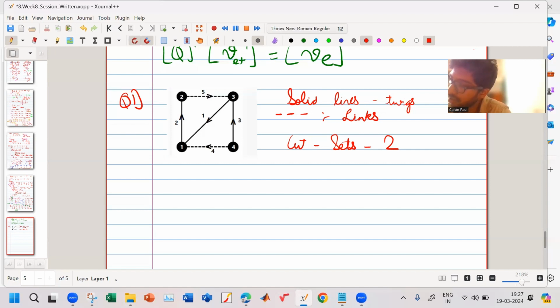One is not possible. Why? If you take it, it cuts two twigs simultaneously. We are taking a cut set across 2 and 5, but we do not get a cut set at node 3, because two twigs are involved, but in a cut set only one twig is involved. Okay, we can disagree, but I'll say there are 3 cut sets.